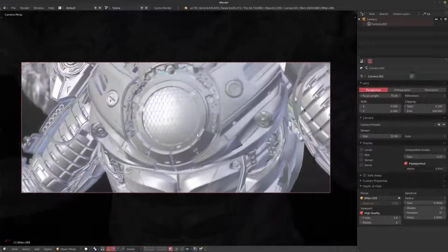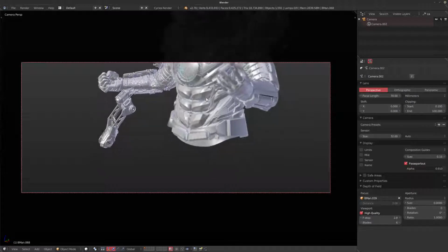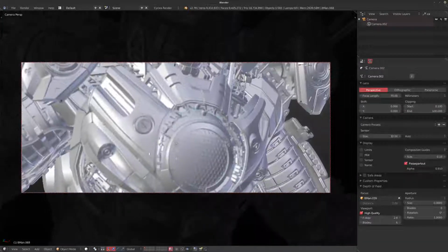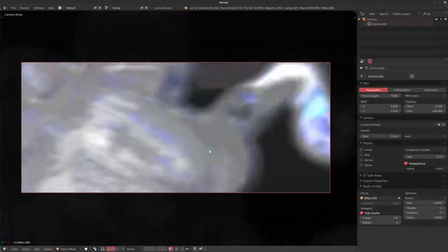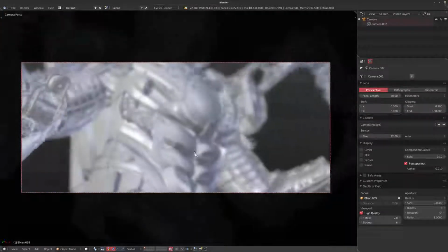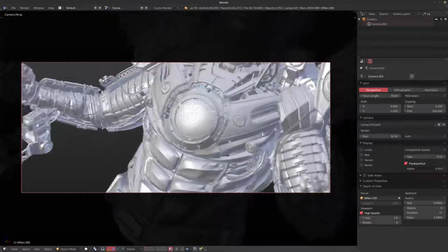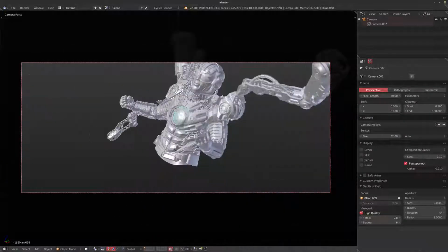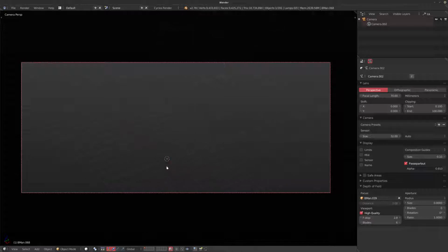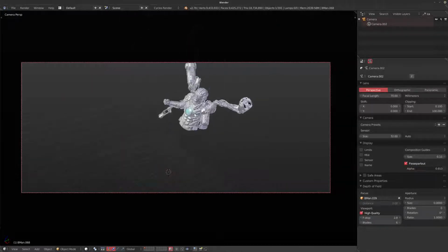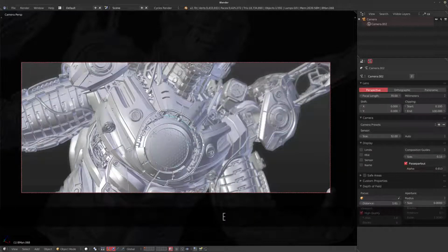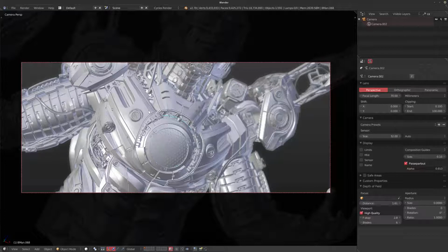Now, I don't know which one exactly it is, but don't forget, I believe it uses the origin of the object to set the focal point. And as you can see, if your origins aren't set up correctly, you're gonna get some really weird results. I know this is happening because my origins are at the very bottom here. There you go. It's at 000 because I reset the whole thing before I started using this file. So you can just delete this, hit the distance again, and again, you'll have what you need.